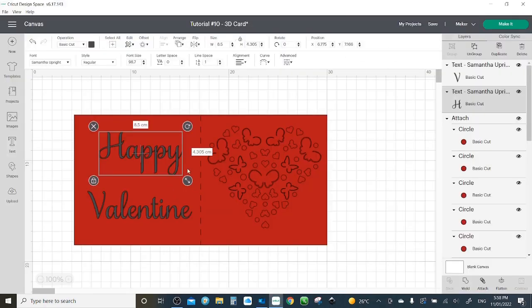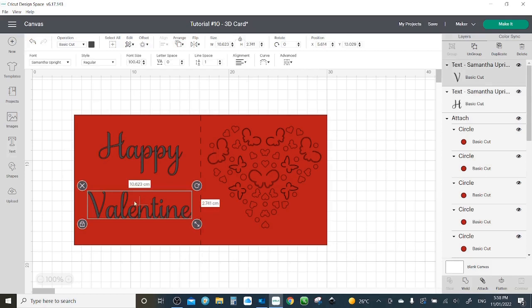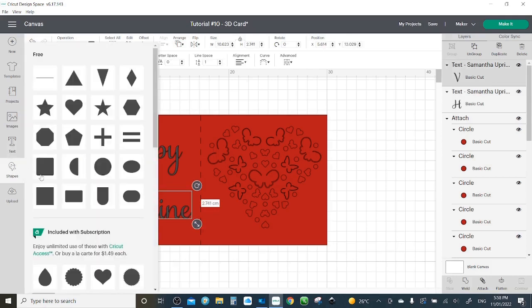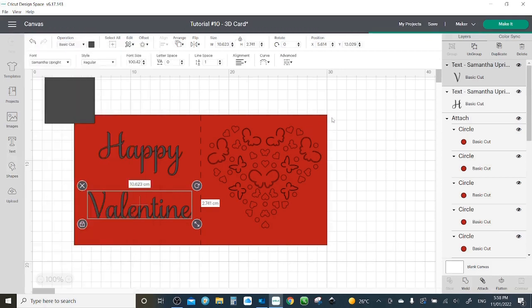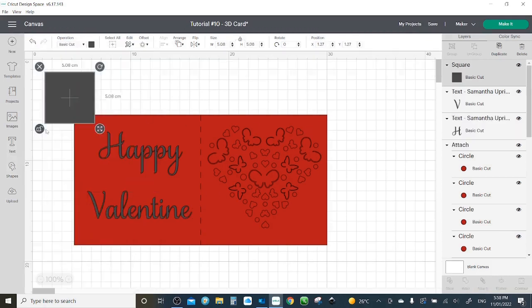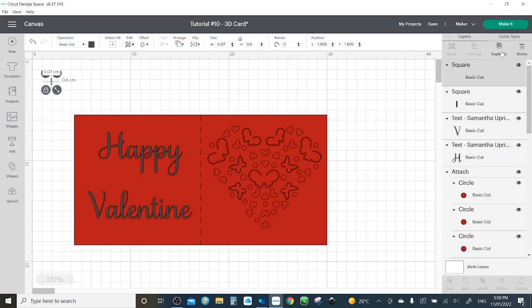And that's because some letters like A, E, P, the loops of Y and the H, have a closed center, and that's called the counter. So to help that counter, you make a little rectangle around 0.07 centimeter width and the height 0.6 centimeter. If you want to do it with the inches, you click on the menu and in the setting change from metric to imperial.